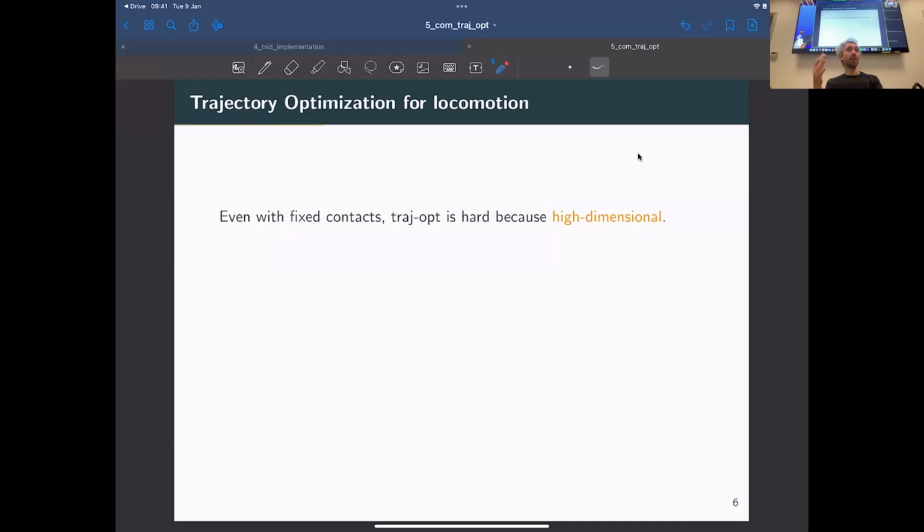So if you multiply that times the number of time steps of your prediction horizons that you're going to use in trajectory optimization, maybe you have 100 time steps. So you have 40 degrees of freedom times 2 to get also the velocity in the states. You get 80, let's make it 100 for simplifying the computation.